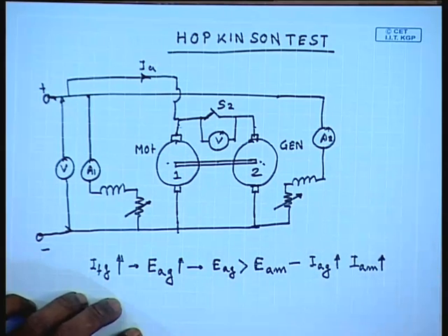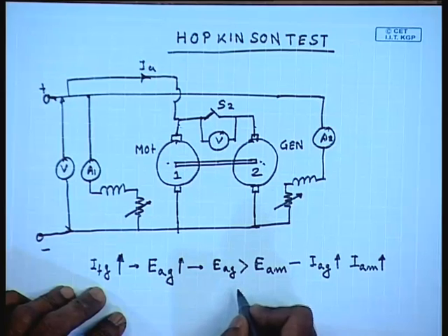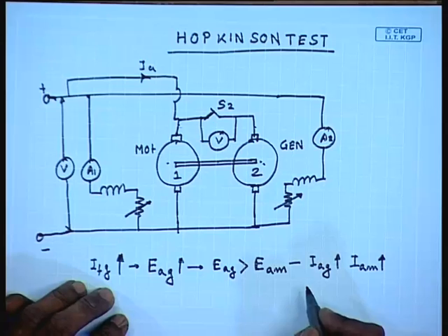So, by controlling the generator field excitation, we can control the loading of the two machines.